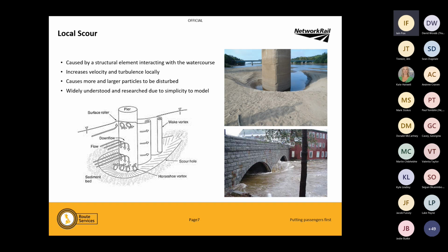But because it has come across this blockage in the water, the water goes in all sorts of directions. The water can go up, where you get this standing wave, which I'll show you shortly. It can flow around the pier, which it does, but then as it flows around, it creates these rolling vortexes, which are just high energy water particles.